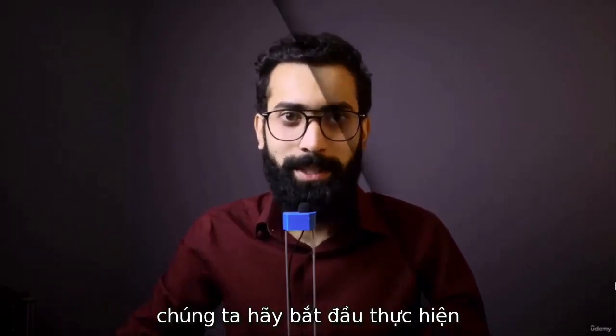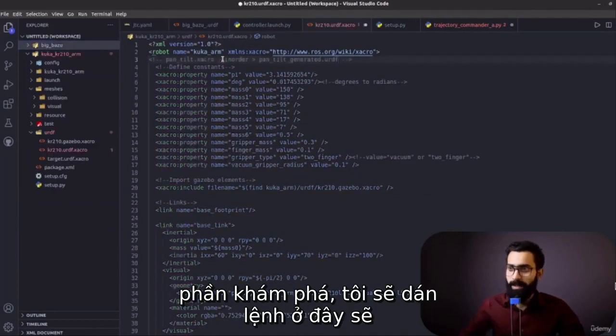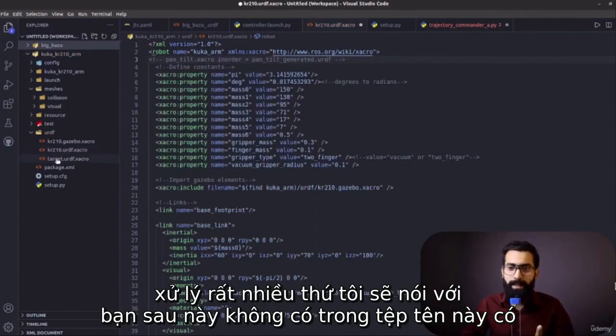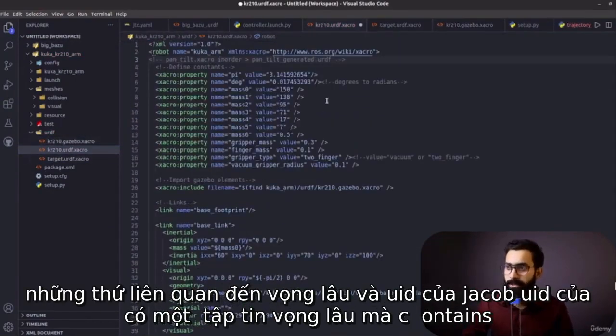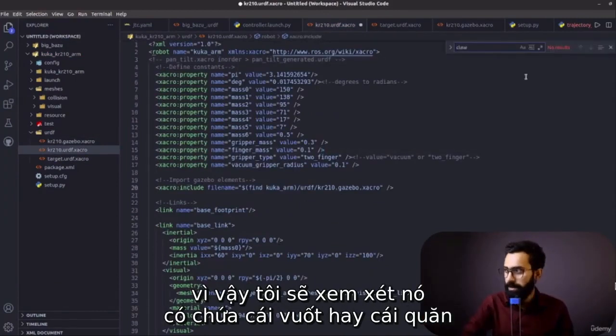Now we are going to convert the Xacro into URDF. It is not a direct process. We have to go through a lot of things and understand how the system takes a look into URDF. So let's start performing the exploration part. I'm going to paste a command here, which is going to be dealing with a lot of things. I'll tell you later. Now, in this main file, there is a target URDF, which is a small one. There is a Gazebo file, which contains Gazebo related stuff, and a URDF Xacro. URDF Xacro KR210 is the main file here. So I will be looking into it. Does it contain the claw or the gripper?